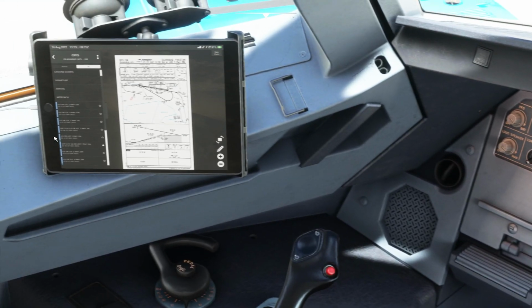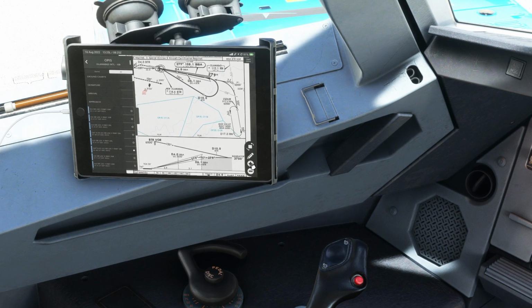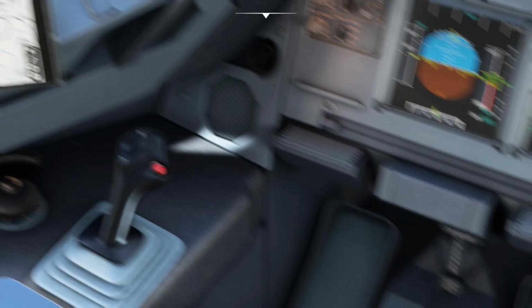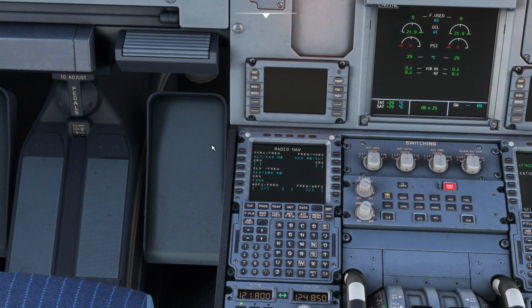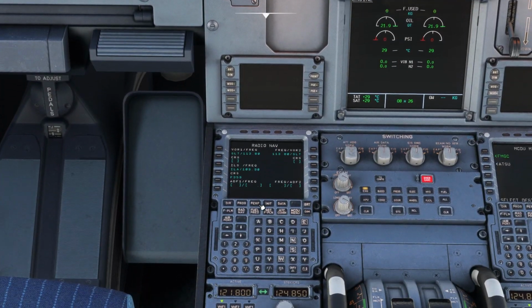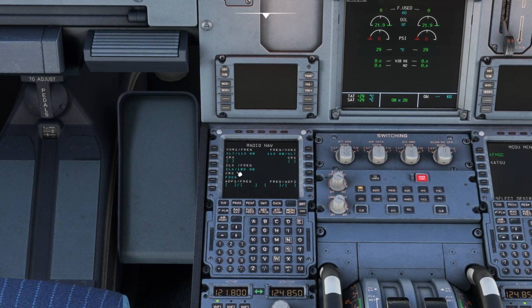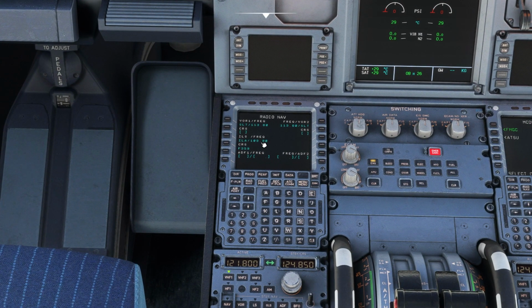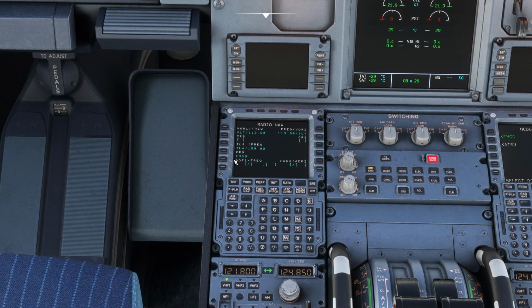for the Islamabad International Airport. You can see, if I go and zoom in, it should be 108.1 ILS IBBA. I think right now it's maybe tuned into Lahore ILS, but once I'm near this airport, it will change to IBBA 108.1. Let's wait for that, but it gets fixed. You don't have to enter the ILS frequency. Yes, the course 359 is coming. This is for the 36 right runway, so this is the Lahore ILS frequency, but I think during the flight it will change to Islamabad.